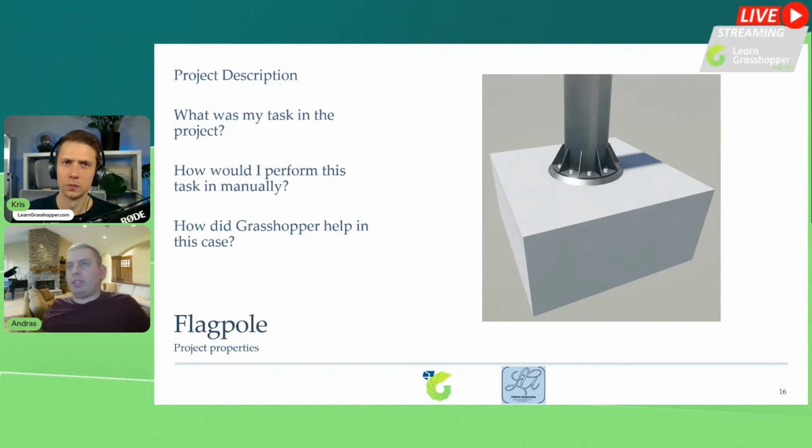A shell model was created in Grasshopper for structural calculations, and this was used to generate the Tekla model. The parameter variables include diameter, length, and the number and position of splices. Considering this, the structure can be fully parameterized.